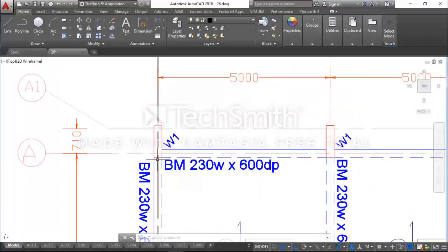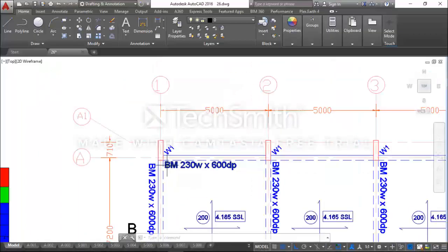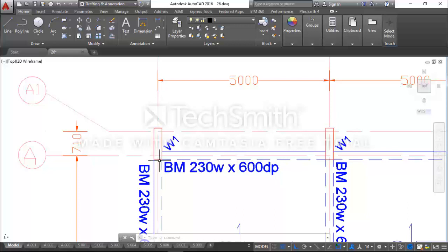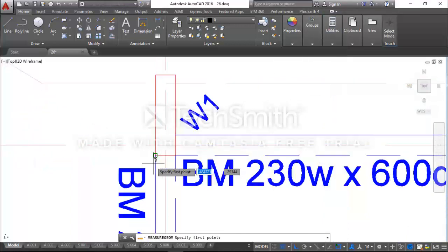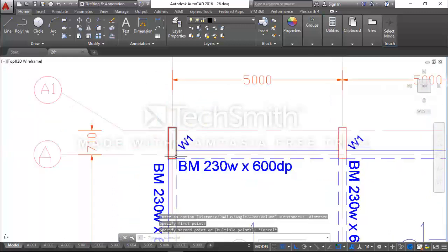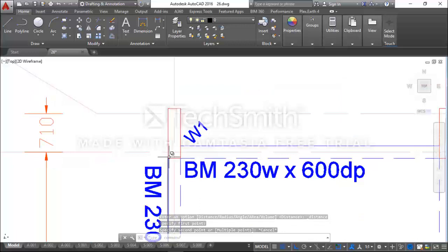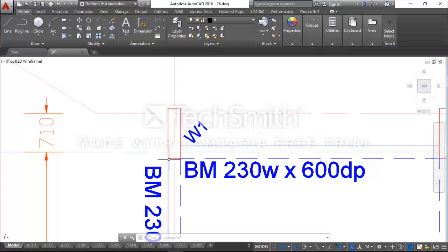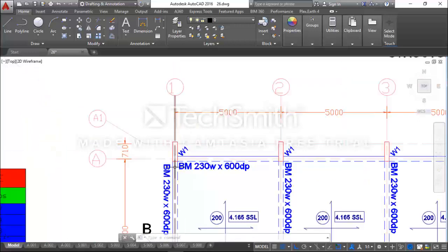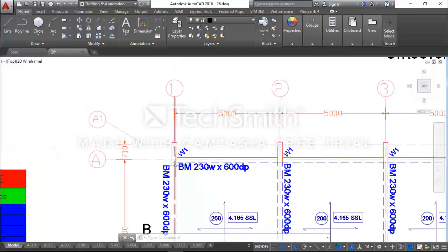So to specify the structural wall, under that app menu I just showed you, you will know that you need to define the width of your wall, B, and that width is 230. So our B is 230. This corner here is the lower left corner of the element. So from this lower left corner of the element to your structural grid 1 is your B2.